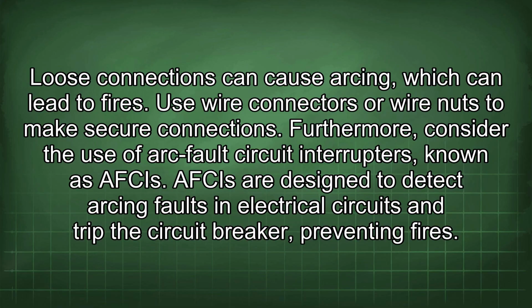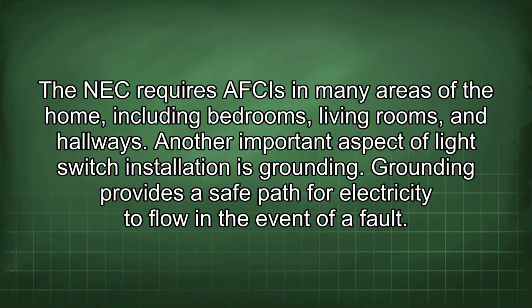Furthermore, consider the use of arc fault circuit interrupters, known as AFCIs. AFCIs are designed to detect arcing faults in electrical circuits and trip the circuit breaker, preventing fires. The NEC requires AFCIs in many areas of the home, including bedrooms, living rooms, and hallways.